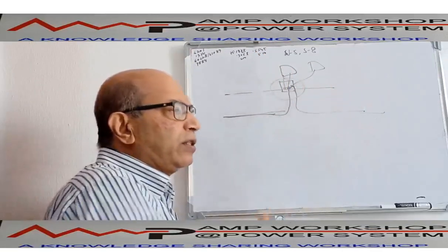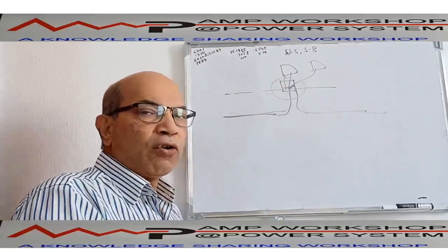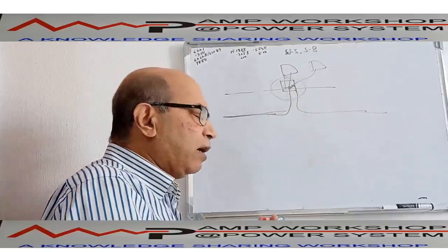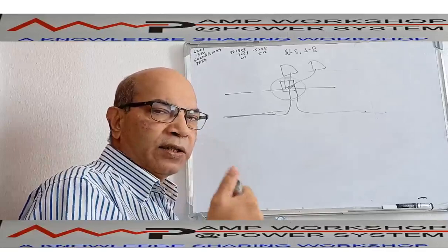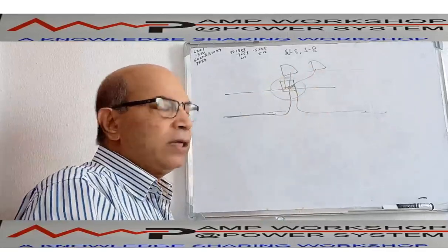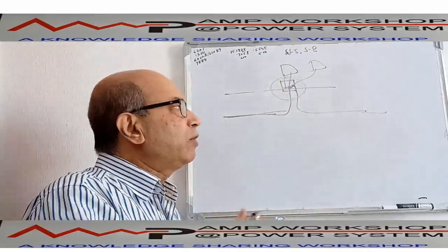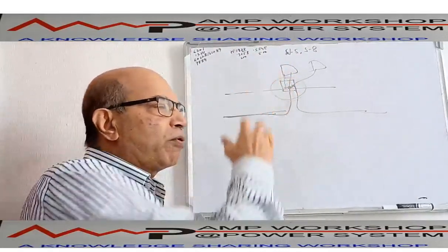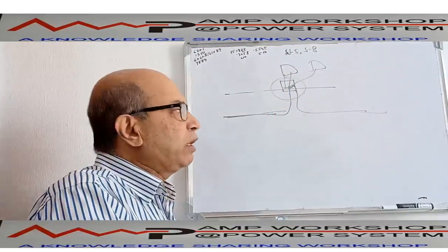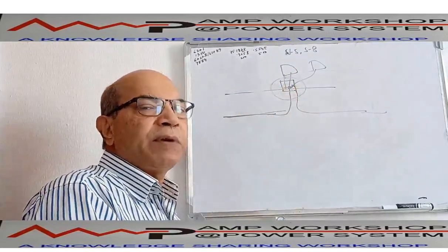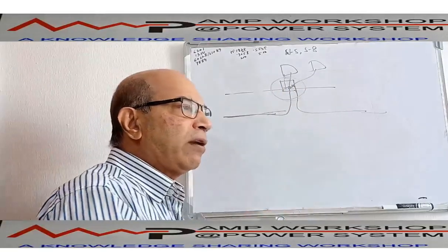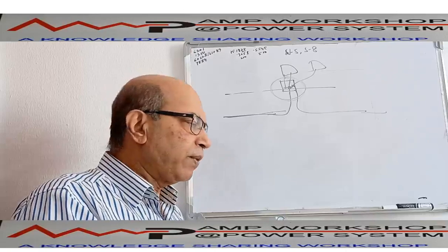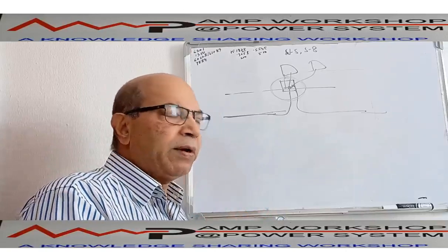So in rural distribution, this type of arrangement is not very cost effective, and maintaining this asset is also difficult. In the rural area, the electricity board people are not moving continuously. Today you install it, and after 6 months this equipment will not be there. It will be stolen, broken, or damaged. So maintaining this property is also very difficult. In this type of case, we cannot use the underground cable system. We use the overhead conducting system.